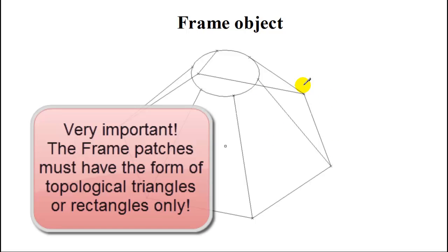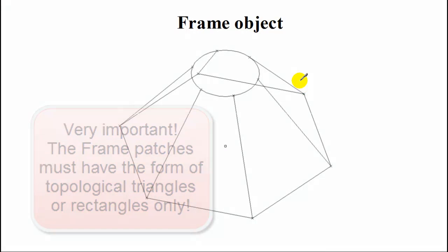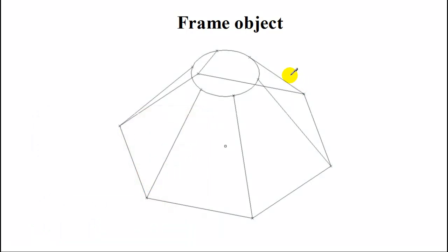The frame vertices usually meet either the points of the cloth hitch to the tent or the points at which the cloth patches should change their geometry. The frame edges are defined depending on two criteria, namely the changing of fabric cloth geometry, for example, and fabric cloth boundary constraints.